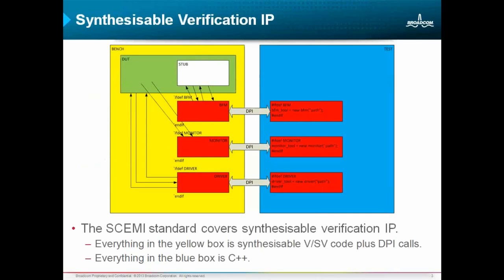Synthesizable verification IP is often structured around the Accellera SCE-MI standard, which sets a standard for how to map these things onto emulation boxes, and essentially it's achieved by having a synthesizable part of the design of your verification IP, which maps onto your emulation box.